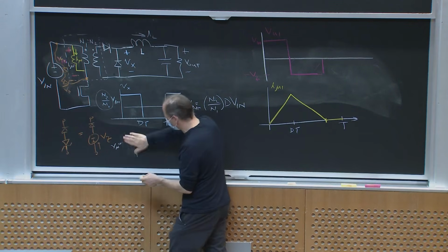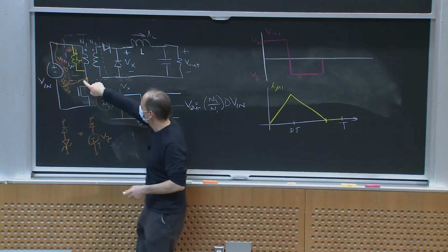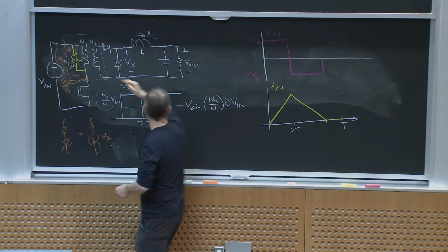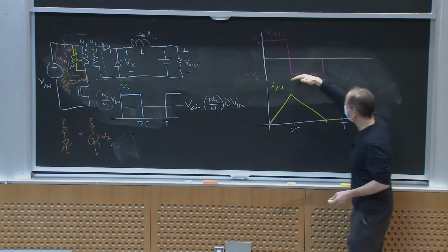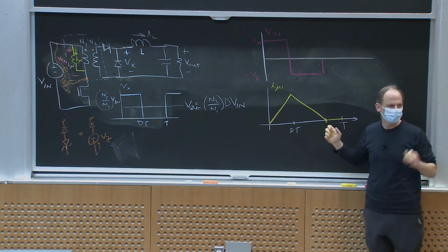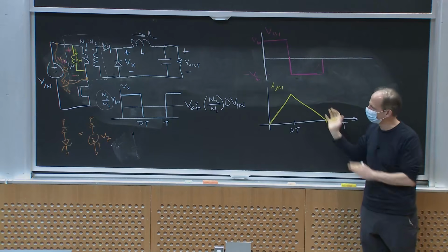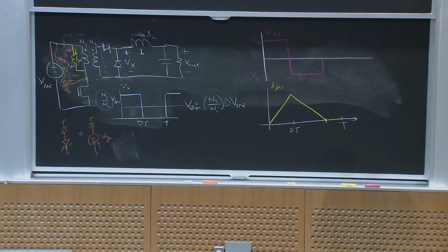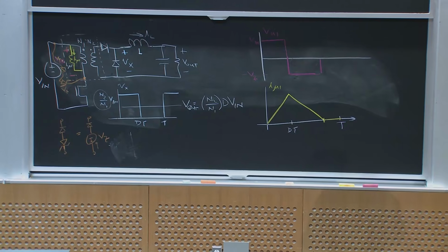Maybe I should have drawn it differently. But essentially, I just got to give this current a path to flow into a voltage source that's going to apply enough negative voltage to drive the magnetizing current to 0. A lot of ways I can do that. The Zener was just sort of my model for the easiest one to show you. Does that explain things? Other questions?